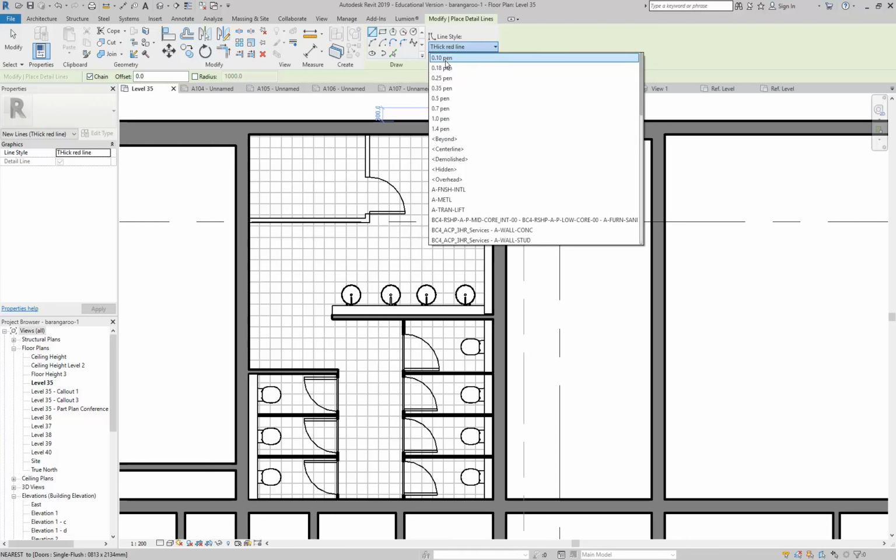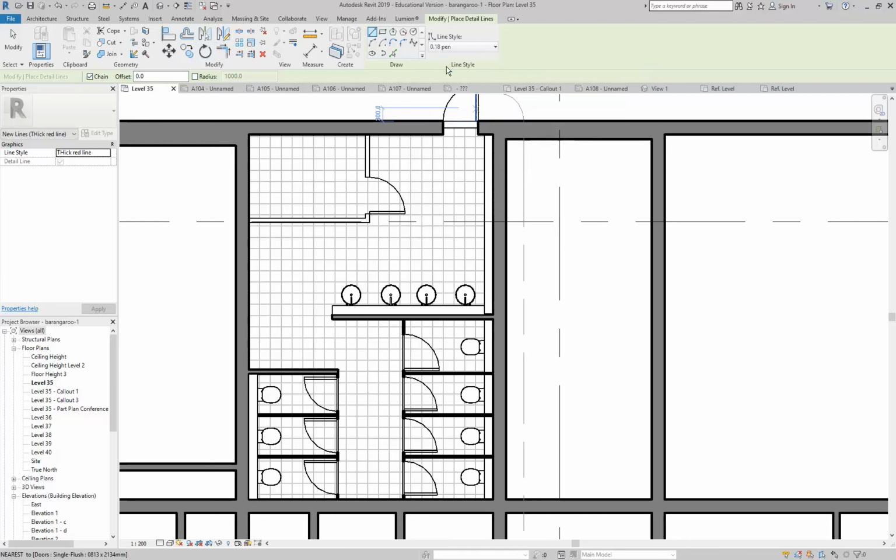So what you can look at though are things like the line weights. That's a good one to start with. So you've got, say, the 0.35 pen. Well, let's go 0.18. So that's a fairly light pen, and then I can just draw lines, which might be for my floor waste, and I might just do it all the way across, and we'll pretend that it's going to go under these walls, which is possible. Not really, but we'll say it is.